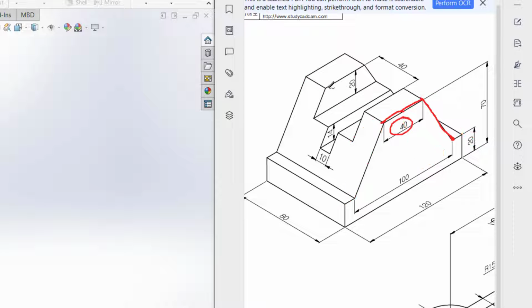After that, in the top plane we can see we have a rectangular cut like this, and for doing this rectangular cut, first of all, I'll draw a center line from here, and from this center line I'll draw two offset lines, and the total offset has a dimension of 40 units, so the half offset will be 40 divided by 2, 40 divided by 2. Then I'll close the shape. Okay, and after that I will cut it to 20 unit.